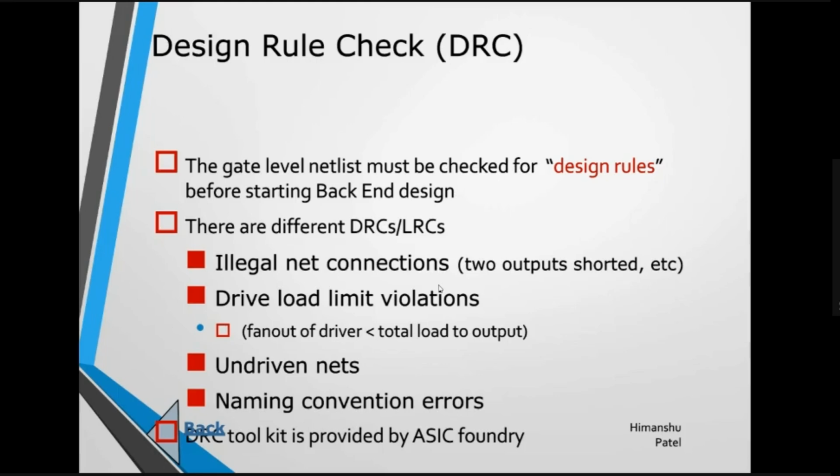Similarly, here you give the inputs of netlist, libraries, clock constraints, reset constraints, all of it, and you tell the tool, I need a DFT insertion with a demux flops and a mux design. There are many parameters for the scanning session. You tell all of this through commands, and you write a Tcl script. The tools are compatible with Tcl scripting or shell scripting.